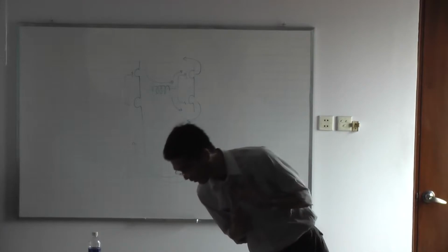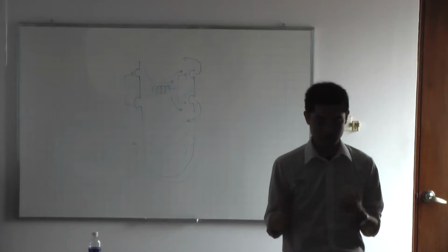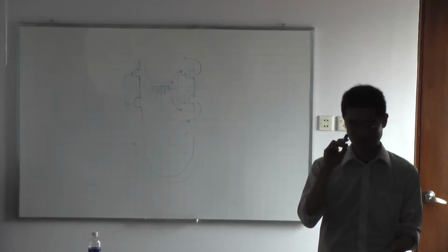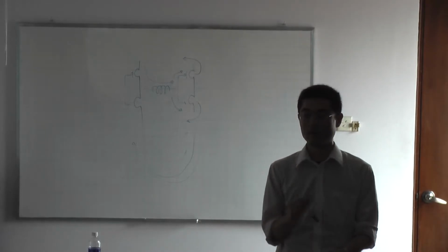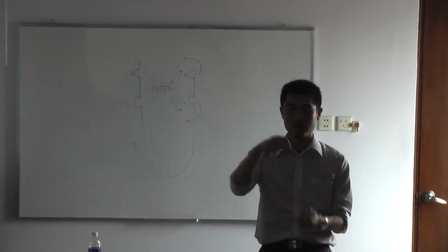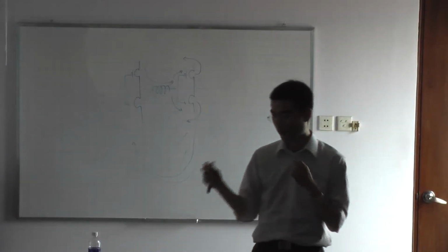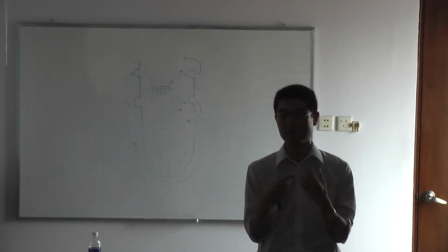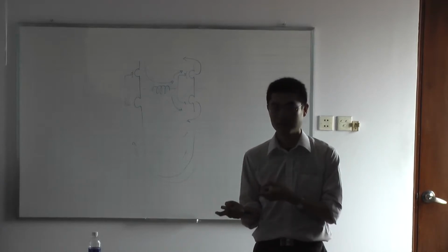The first one is the electrolytic capacitor. The capacitance of this capacitor is very large, but it has less loss. It works only at lower frequencies, and it has very large inductance on the wires. It does not have high frequency characteristics, so we can use this only for low frequency signals.